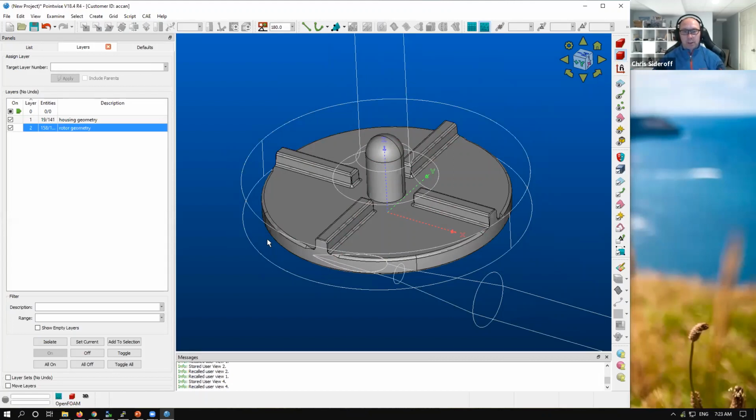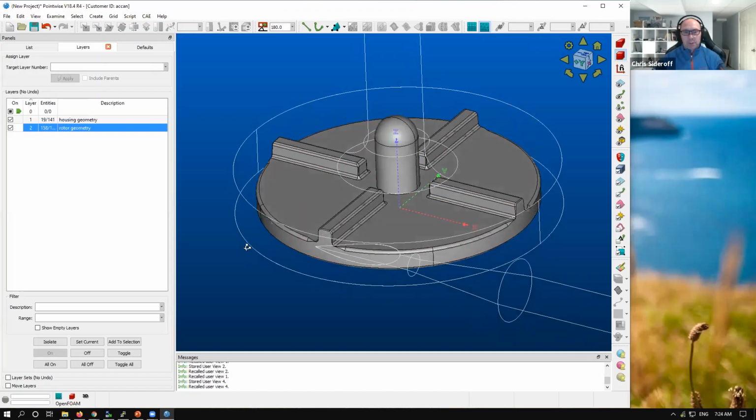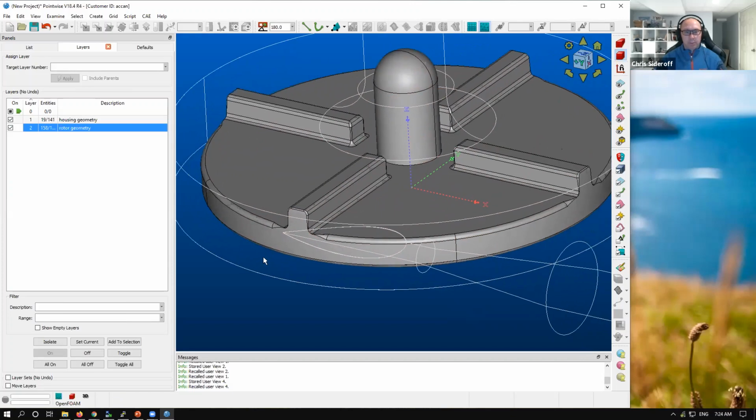What it does is that on the edges of the actual geometric surfaces, it's going to create connectors. This is one of the nice things about Pointwise being a bottom-up method: getting your grid points on the features in the geometry is automatically part of the process. We don't have the snapping process or geometry conforming process that the top-down methods do. But one thing that can happen is that, as a byproduct of how the CAD software decides to make the geometry, which doesn't really help us from a solution or meshing standpoint, it creates an unnecessary number of surfaces.